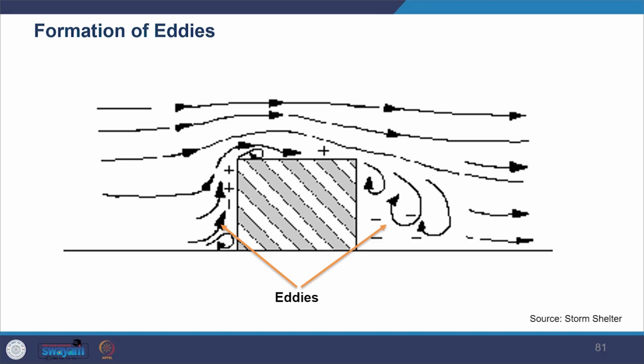Also, whenever tall buildings are adjoining the facility, wind can sometimes give rise to high ground level concentration. So that can also happen. You will see why such a situation arises: due to the formation of eddies around the building that make the plume touch the ground much closer. In the absence of the building, these plumes would not have hit the ground. It is usually understood that building downwash problems occur if the stack height is less than 2.5 times the height of the building above which it projects.